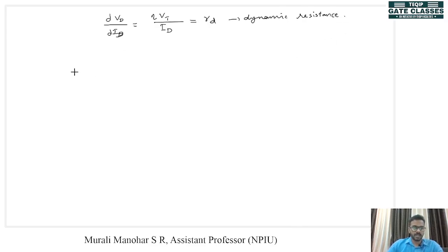Okay, now if we redraw the circuit for small signal analysis, we have to remove all the DC sources. There is our input Vi, the AC input only, signal only, in the resistance 9900 ohm, and now the diode's DC sources, that is 0.7 volt DC, cannot be considered because that corresponds to a DC source, and in AC analysis we cannot consider them.